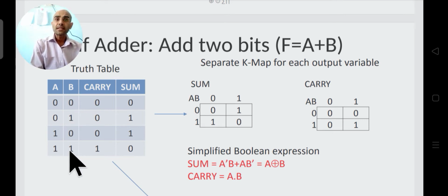Once we have done this, then depending upon the functionality this specifies, we have to write the outputs. As it is an addition operation, it will generate a sum, and some carry forward will also be generated. So the output will have 2 bits, or 2 variables. I have written them as sum and carry. You could write them as s and c, or x and y as well. It is your choice. So if I add the 2 bits 0 0, the sum will be 0 and there will be no carry. I have written that here.